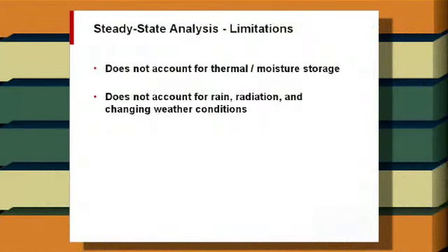It's a steady state analysis, right? Just one condition, one snapshot in time. And this particular model does not account for thermal or moisture storage, right? Can't do that. And it does not account for rain, radiation, and changing weather conditions, right? If it's sunny out, if it's overcast out, you have to use other models and crunch them together to make that work. And that's where Eric said, sometime somebody's going to come out with the overarching do-it-all software. It's just not there yet.